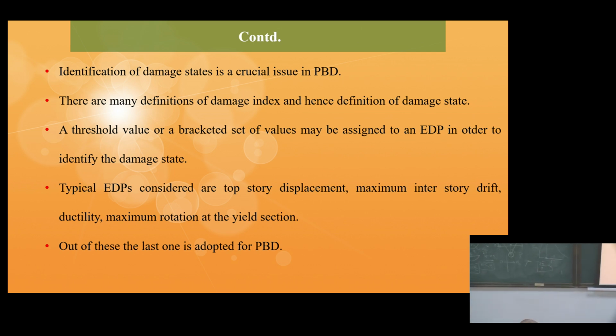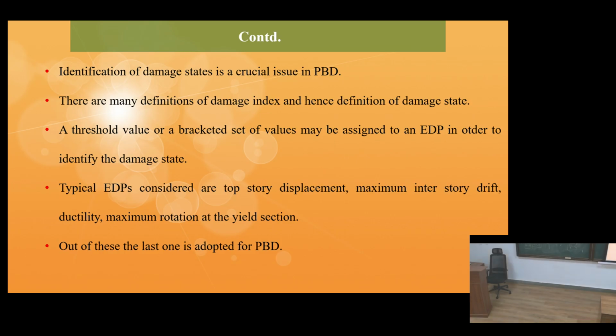Now the next point is, as I told you, the identification of damage states. In PBD, that is the most important thing. You are saying that I must have damage up to this level, and I'll design my structure according to that. I will not permit beyond that.